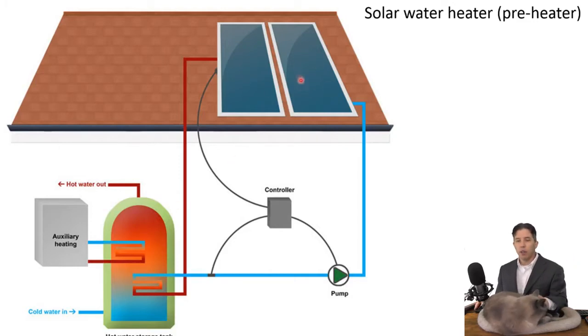You might run it through these solar preheaters, and it might warm it from 40 maybe to 80 or 90. So then you've got 90-degree water going in, and you have to warm 90-degree water to 140, which doesn't take nearly as much energy.